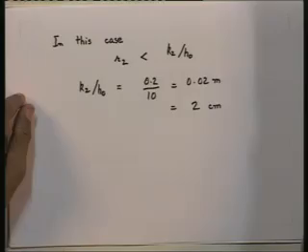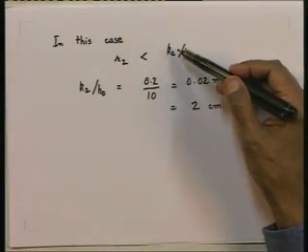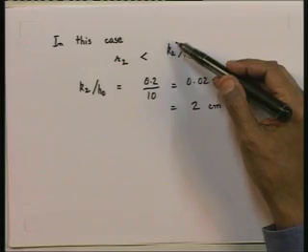Keep in mind this situation does not happen very often. When does it happen? It happens when K2 is high, that is, the thermal conductivity of the insulation is high. This situation will also occur when the value of h0 on the outside is low. Then the combination K2 by h0 will give me a high value of R critical, and then only R2 may be less and Q by L will first go through a maximum. So, it will occur only under these situations, keep that in mind.